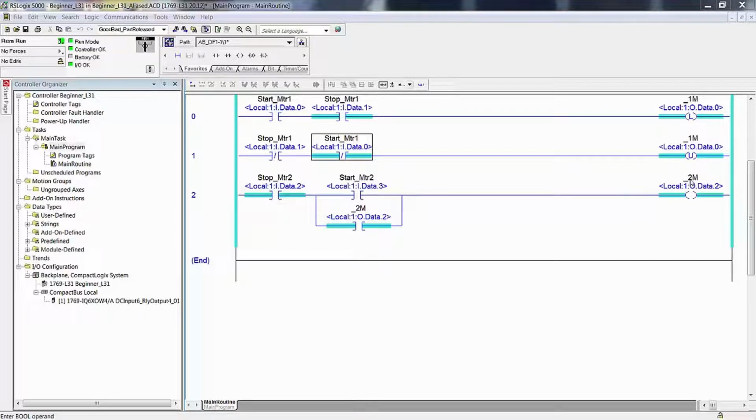So if this were a relay, you'd call this relay CR2, control relay 2. This would be CR2-1. It would be a contact that's mechanically connected to this coil. You push the start button, it energizes this coil, closes this contact. So now you have current flowing through both of these contacts to this relay coil. When you let go of the push button, it continues to flow through its own contact. It is self-sealing. It is sealing logic.